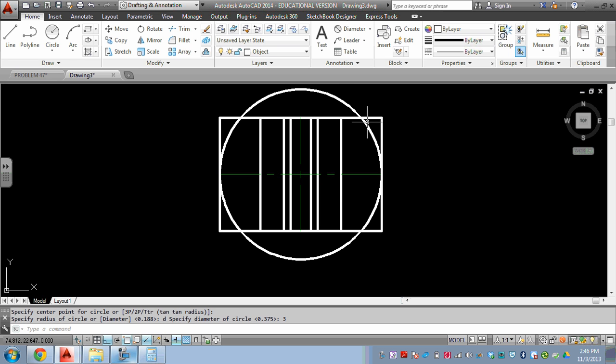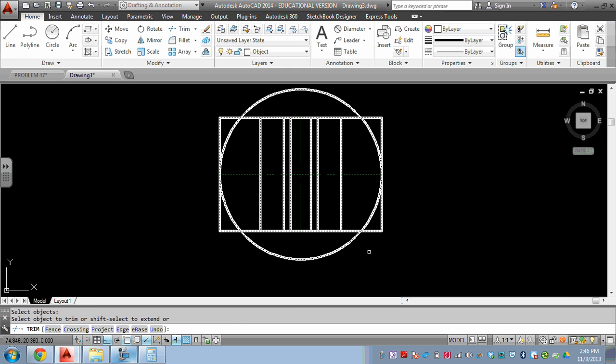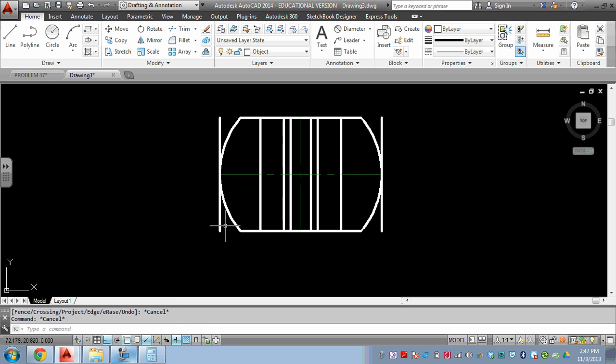Right there's that object. So now we can do a big trim, TR, again. Select all of it, trim that, trim all this, woo, undo that. You can hit U to undo, trim that, trim that. Then you can select this and hit E for erase. Repeat the command with the space bar, select it, hit space again.